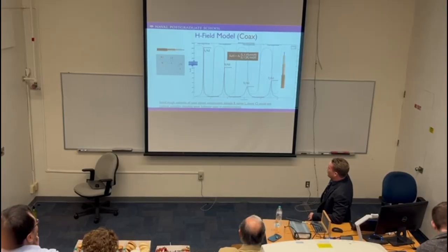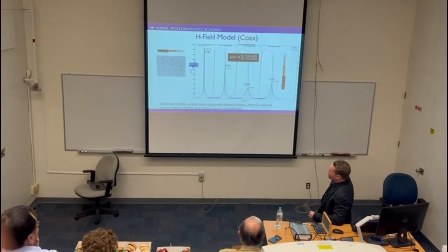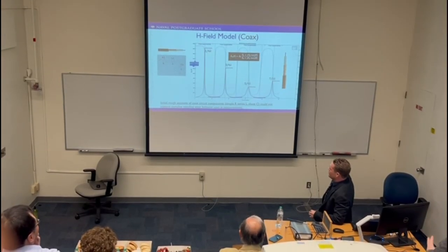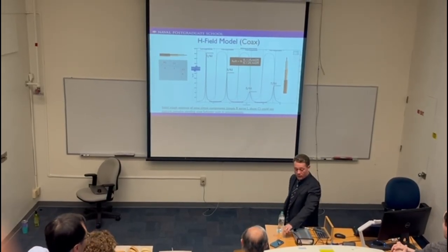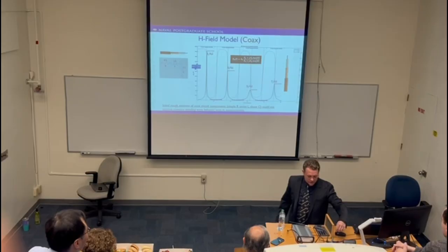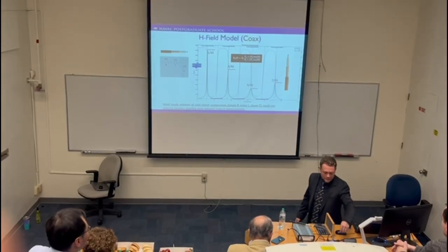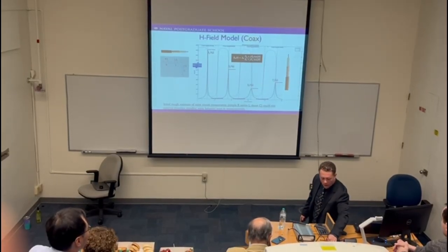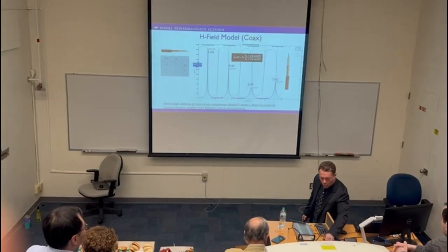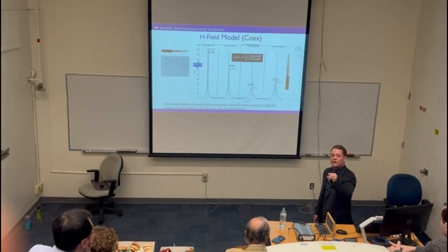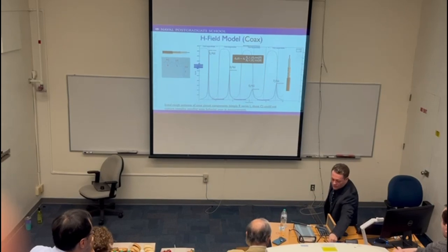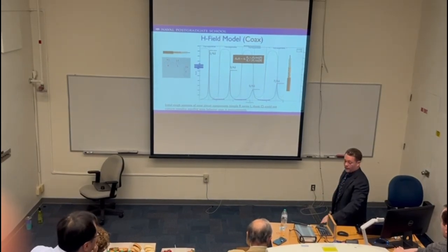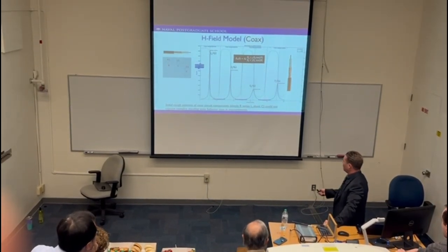You need to go into much more complex and cascaded type circuitry to look at what happens when you have a coax cable and you basically short it. That's exactly what I did here. I went from 50 ohms of my coax to 0 ohms. That's a horrible mismatch. It's going to cause standing waves. I'm certainly not going to be able to use a basic RLC type circuit, especially in the frequency range that I'm working at, to adequately model that.